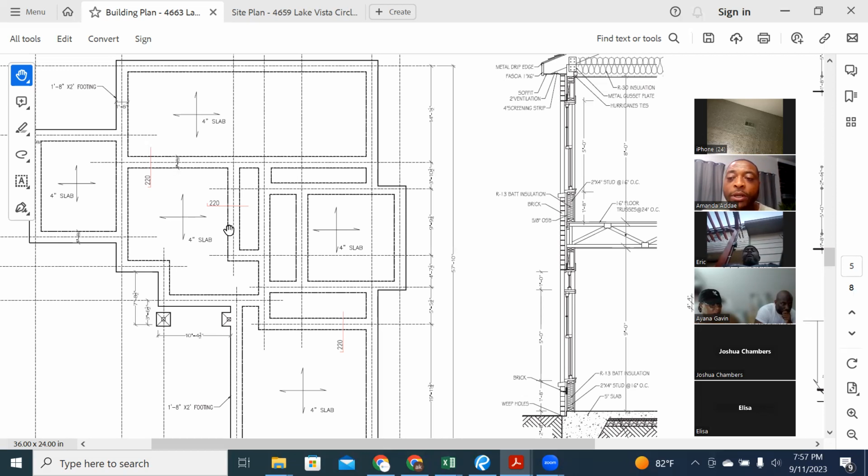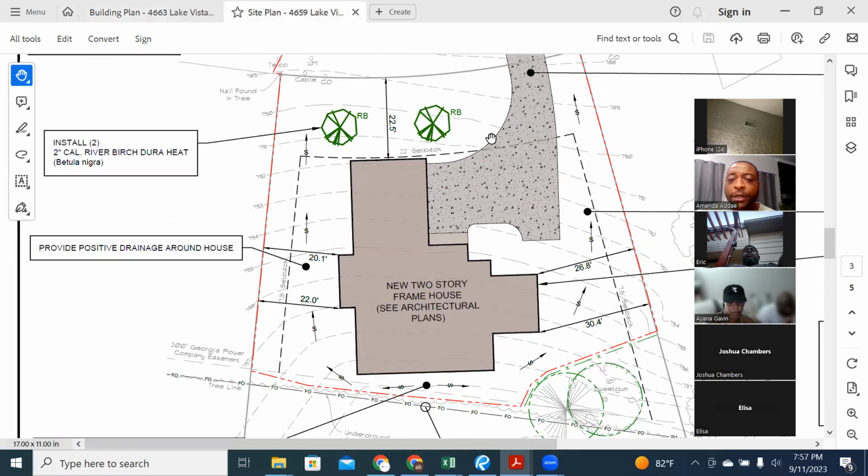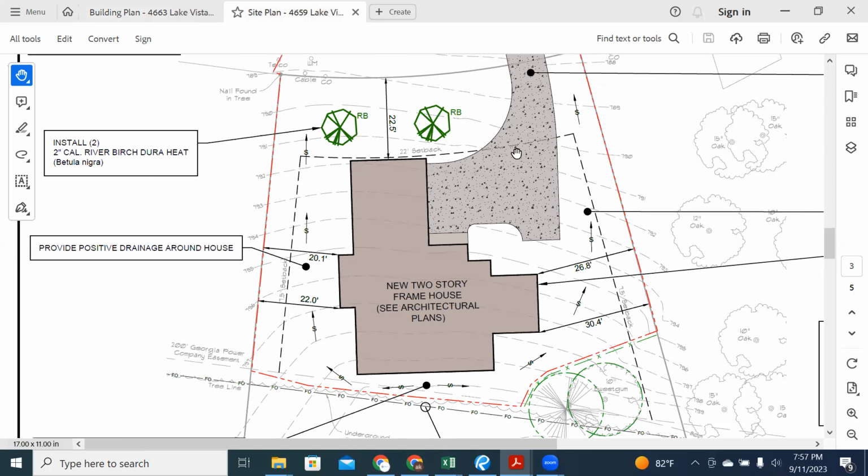And then they're going to ask you if you want fiber. Sometimes, depending on the weather situation, you want fiber to harden up the concrete a lot quicker, so your concrete guys will ask, hey, do you need fiber? Another thing they'll ask you, which is in the video, and let me bring out the site plan so it makes sense to everybody, is whether there is going to be a pump truck or not.